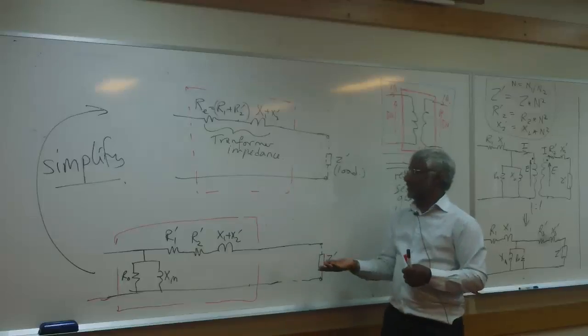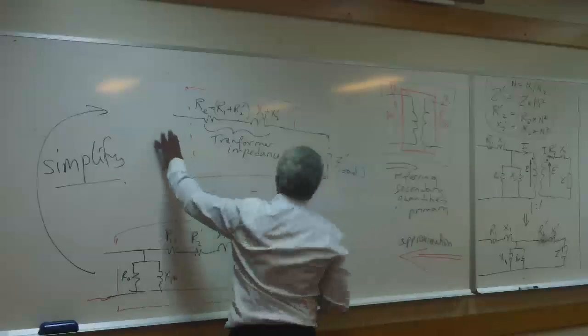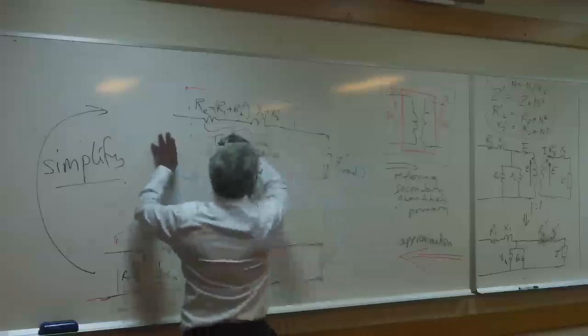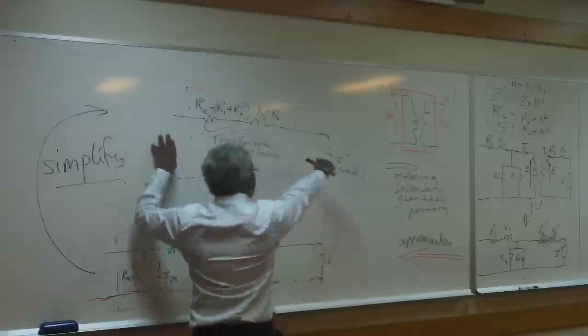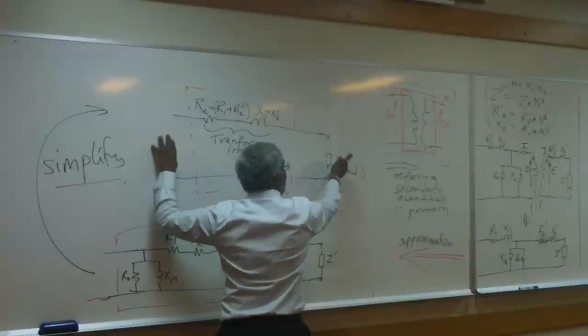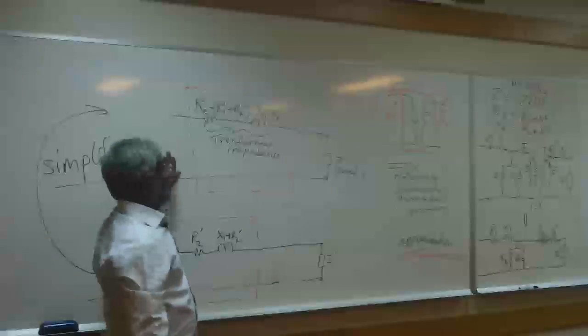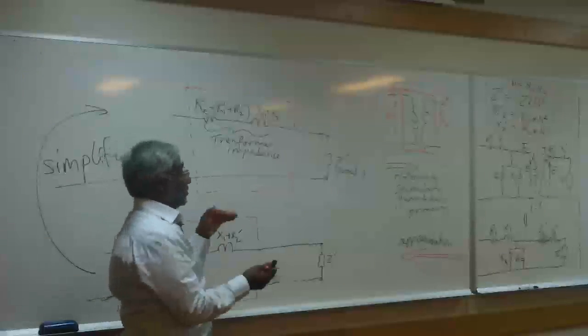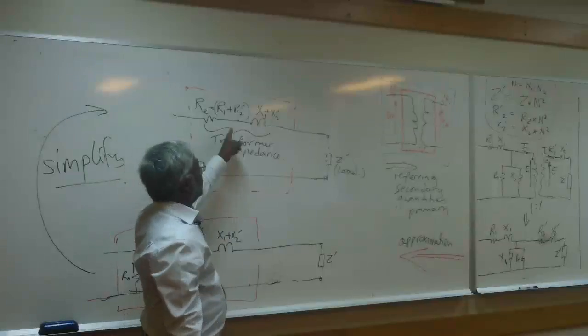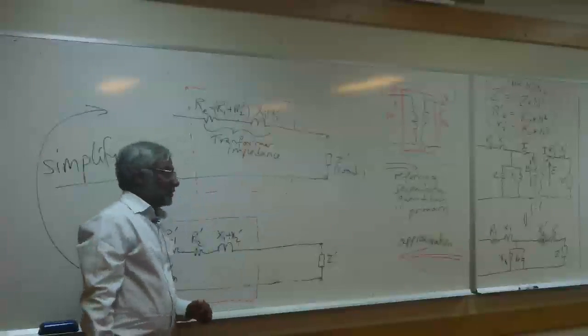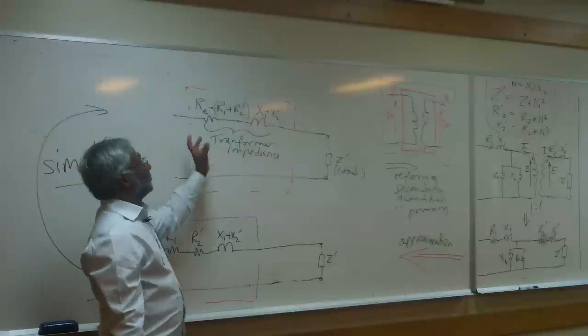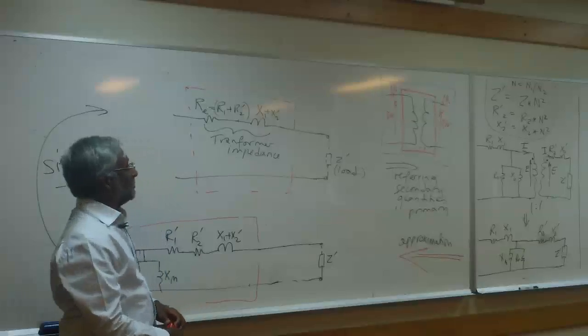As you can see, if you put whatever voltage here, with more leakage and therefore more impedance, this fault current on the secondary side is going to be less. So if you wanted to reduce your fault level, you could have more leakage. So these are reasons why you would have different impedances.